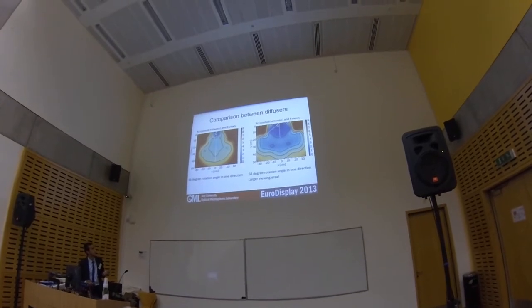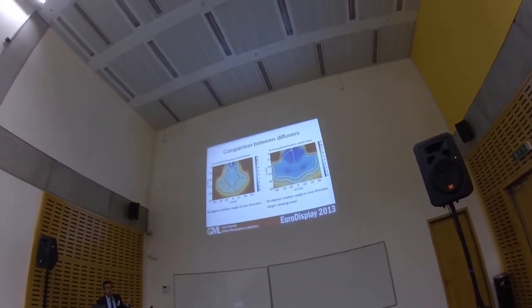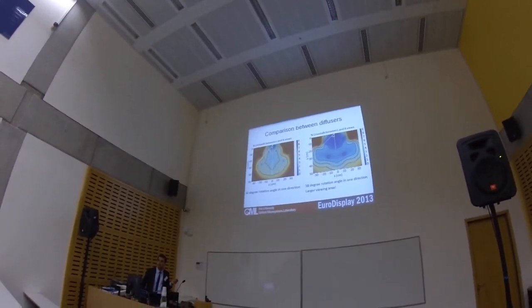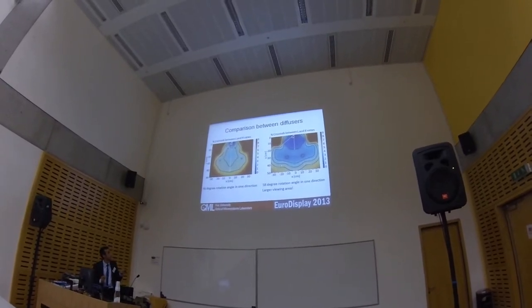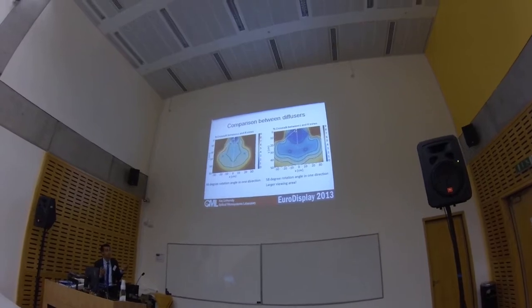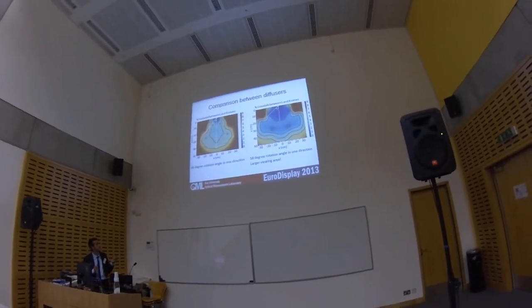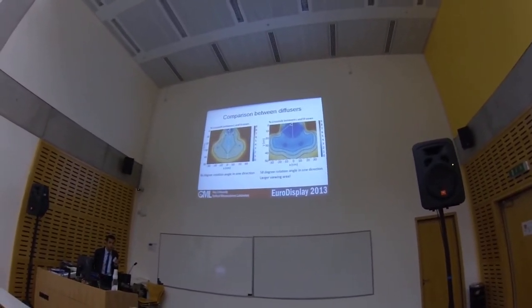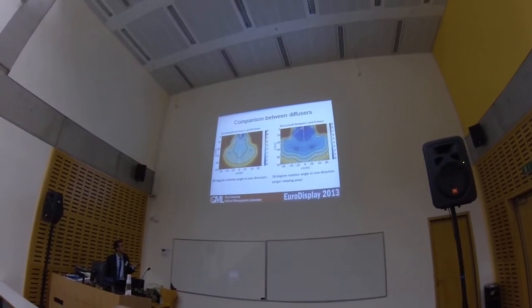And this is the comparison between diffusers. First, we used that 40 by 0.2 degree aperiodic diffuser, and then we decreased the diffusing angle, and we achieved a larger rotation angle, so that we achieved a larger weaving area. First, it was a 46 degree rotation angle. Now it was a 58 degree rotation angle. And we reduced the crosstalk values.